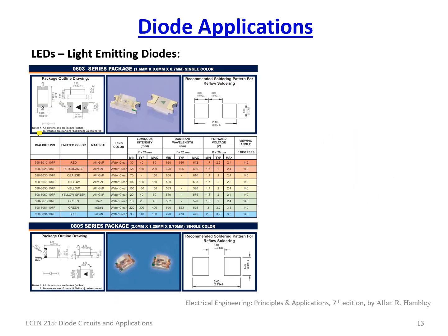So here's an LED data sheet showing very similar conditions to what we were looking at earlier. For instance, the chief difference is the forward voltage is usually much higher. So typically it's like 2.2 volts, depending on certain colors. For instance, blue is 3.2 volts. Green is anywhere between 2 and 3.2 volts.